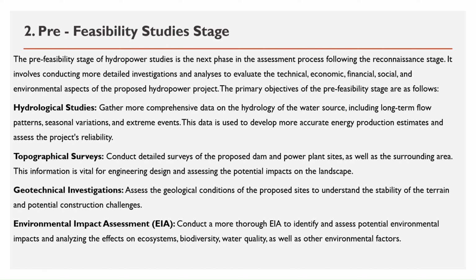Topographical surveys. Conduct detailed surveys of the proposed dam and power plant sites, as well as the surrounding area. This information is vital for engineering design and assessing the potential impacts on the landscape. Geotechnical investigations. Assess the geological conditions of the proposed sites to understand the stability of the terrain and potential construction challenges.